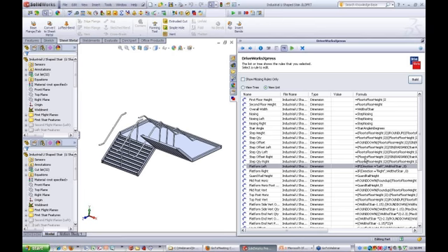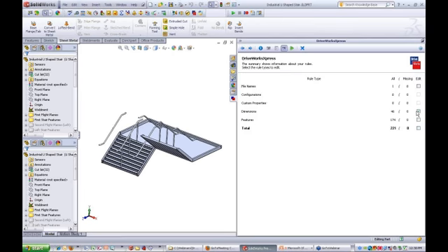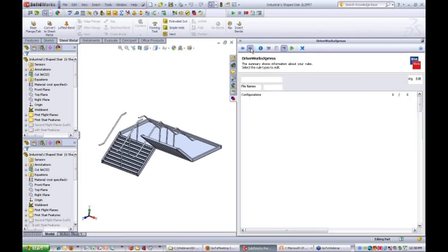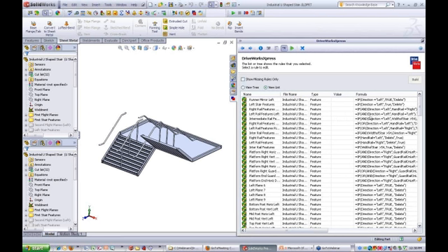Once everything's set up in there, I should just show you a quick look at the features. Because in features you often get things like delete or suppress. So the idea is in dimensions you control the actual value of the dimension. In features you control its state. Is it suppressed, unsuppressed, deleted, all depending on the data entered into the form.